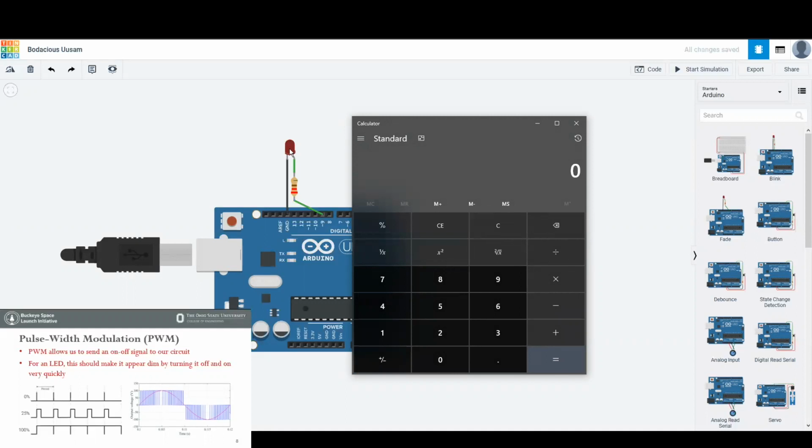So we need 2 volts over this, and we can supply 5. So it's a total difference over the resistor of 3 at 20 milliamps. So if I do 3 divided by 0.02, 150 is actually the minimum of what we need. They use 220.